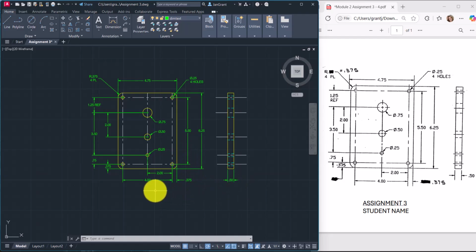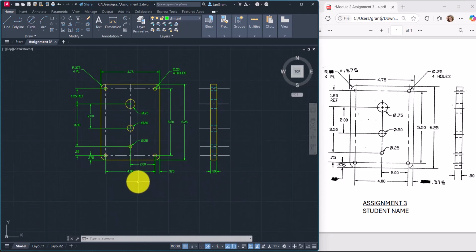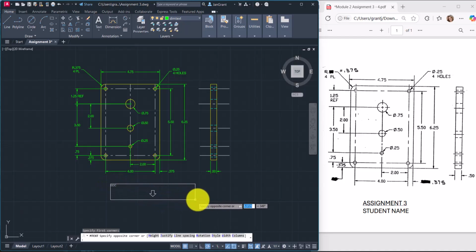Okay. So now let's add our text and create our PDF. I'm going to show you how to create the PDF so that at the end of the class, you'll have it to create your portfolio views. Right. So we're going to the big A there. Click on this multi-line text we did this in our first assignment. You can kind of see the ABC, so you may not have to change the height, but we'll place it as the default height and then take a look at changing it once you already place it. So click in space, pull your mouse across and click.